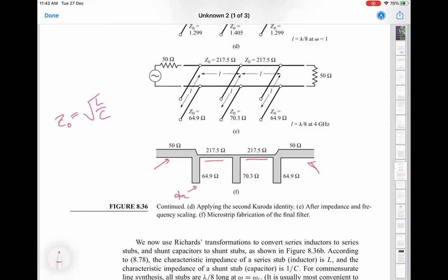Essentially, the capacitance to the ground becomes very small. So let me try to qualify that a little bit better. It's basically saying, why is the wave confined to this transmission line, right, as opposed to just an open wire? It's because of the presence of the two conductors. But the fact that you have free space and electromagnetic waves can propagate is basically this. If this confinement doesn't happen very well, then you will get radiation, and that becomes worse as you make the lines smaller and smaller.